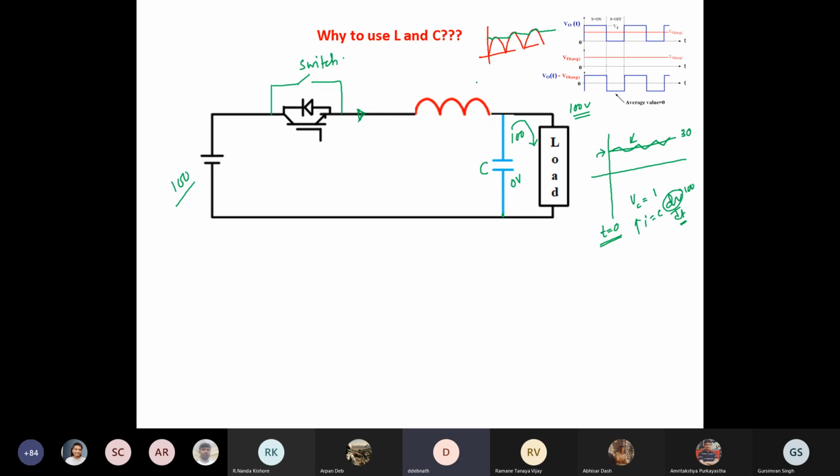Inductor current has to go to 0, right? Yes, sir. When the switch is on, inductor current was having some value. As soon as you turn off the switch, inductor current is going to be 0. So what is the problem with this technically? Let it go to 0. Why should I bother? There'll be a very high voltage across the inductor.